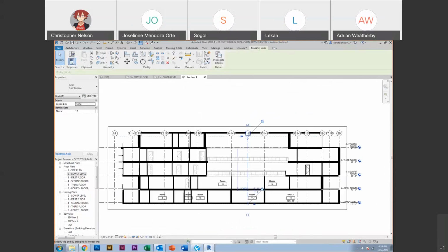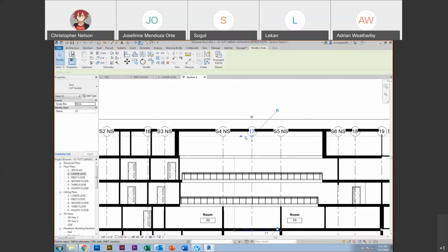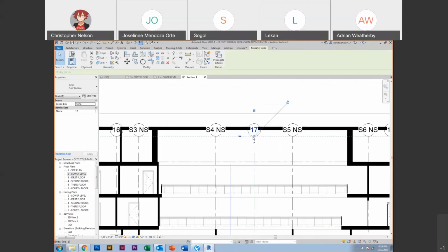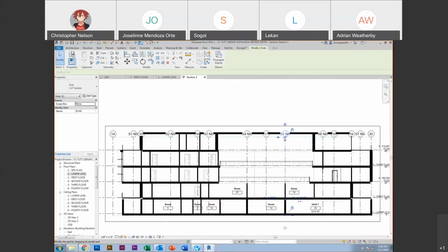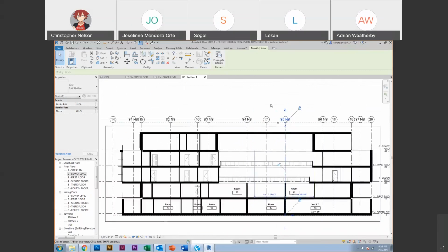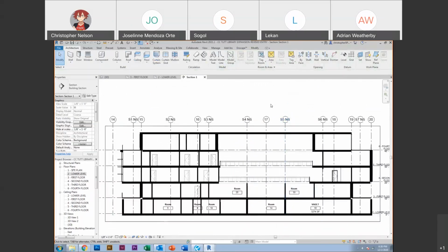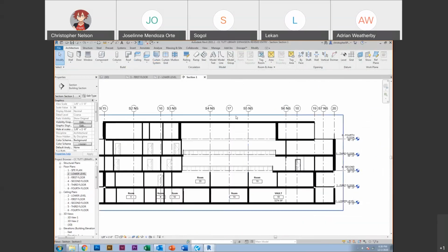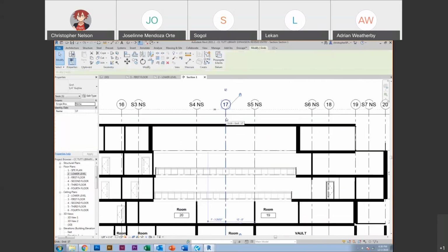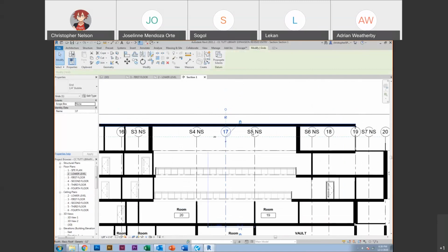And then same thing goes with the grids. Your building is a little taller than the grids. So you click on one of these grid bubbles. In building sections, not always, but most of the time in sections, it'll give you the option of 3D, which is here where my cursor is. If I pull it up, it'll pull it up for all the ones across all my views. And if I just wanted to do it per view, I can click on it and say 2D or 3D. So right now, 2D, and I could play with it here.